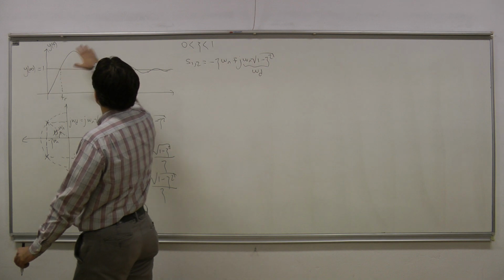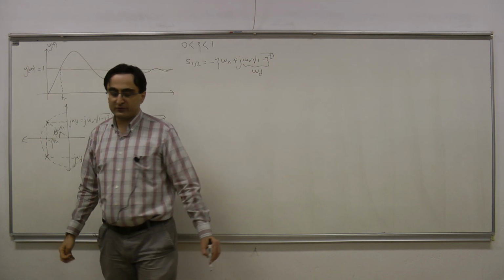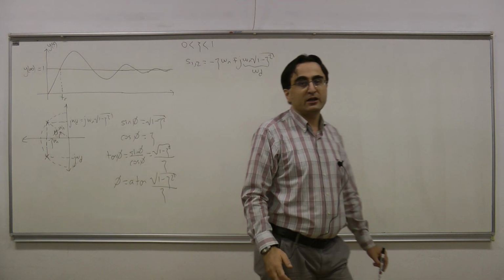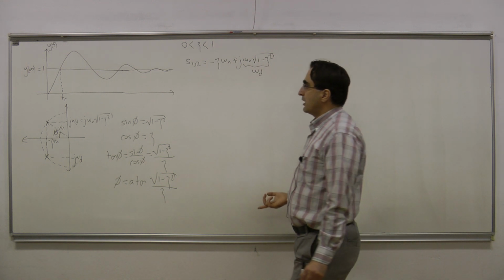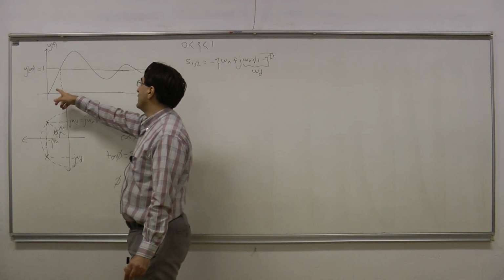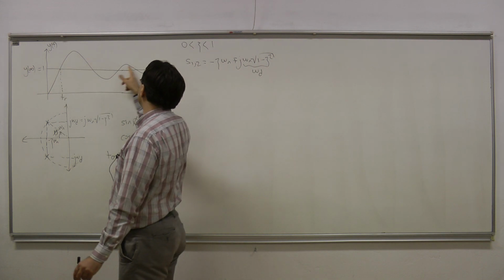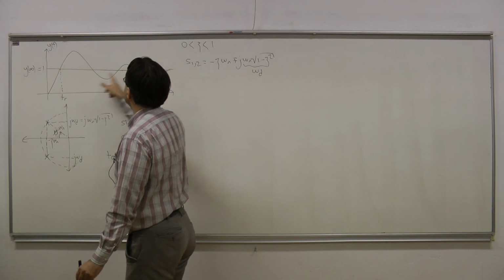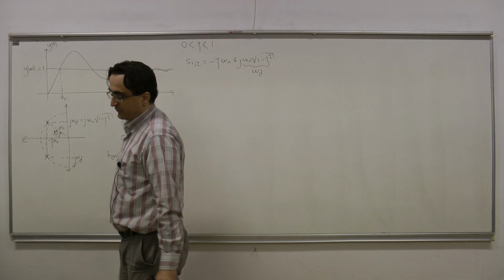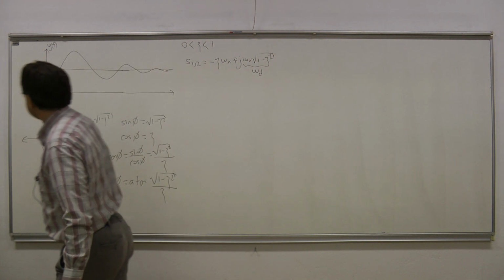Even if this response is scaled, even if the second order system is not in standard form, that is going to be our definition of the rise time. It is the first time instant that the response intersects y infinity, the limiting point of this response.